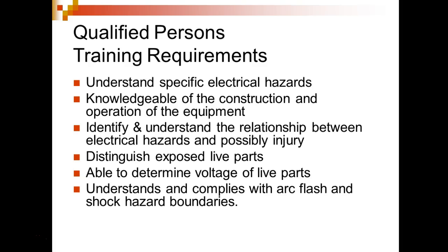Understand the specific electrical hazard, knowledge of the construction and operation of the equipment. Identify and understand the relationship between the electrical hazard and the possibility of injury. Distinguish exposed live parts. Make sure you understand if they're exposed and they're live. Be able to determine the voltage of live parts. Understand the arc flash and shock boundary hazards. Being able to know what you're getting into before you get into it, right?